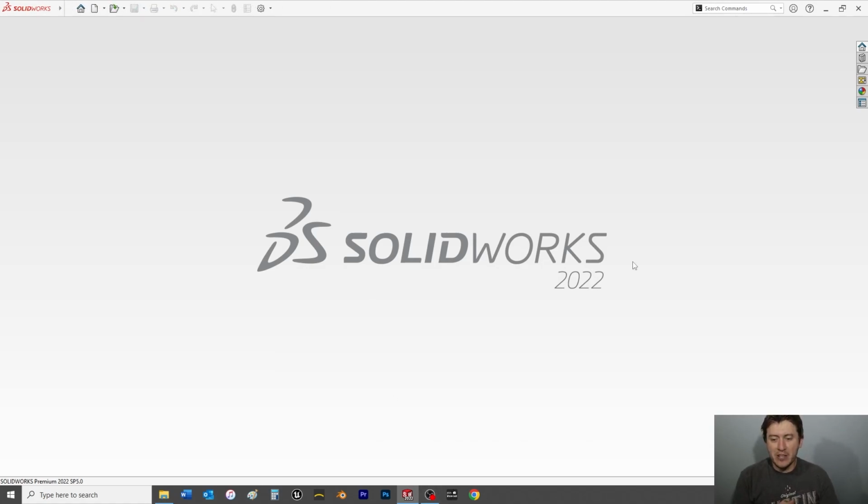Okay, after you've made your units and dimensions standard selection and press OK, SOLIDWORKS will load and bring you to this beautiful screen here. Now what I want you to do is focus your attention on the top left corner here where you see the little red SOLIDWORKS logo, and you'll see a tiny little right arrow. Hover over it and you get File, View, Tools, and this little pin icon. Click the pin icon to lock that in place from hiding. This is a nice feature to have in place so that every time you open up SOLIDWORKS you can instantly get to File to create a new part.